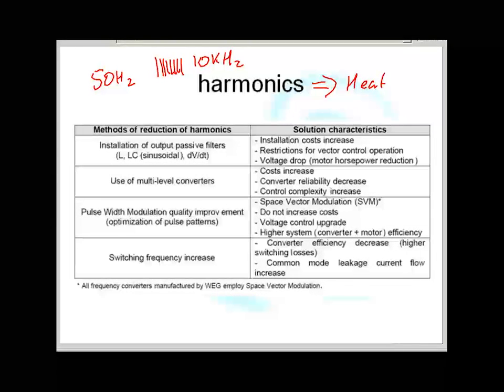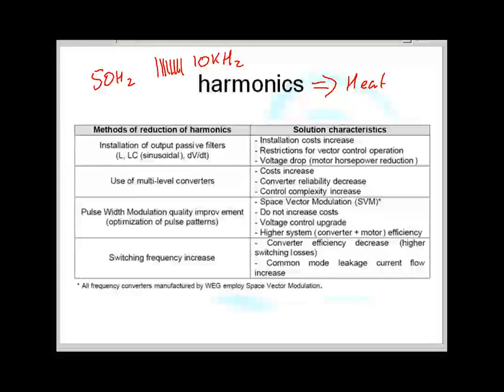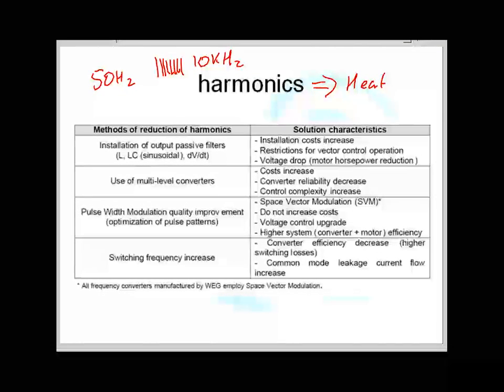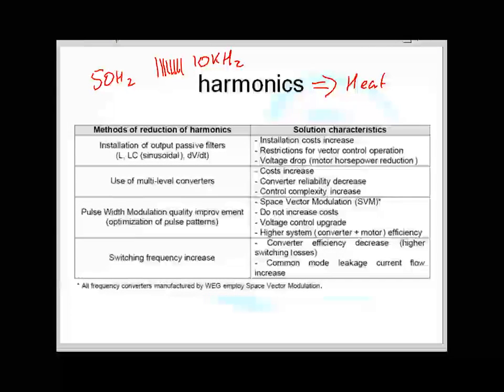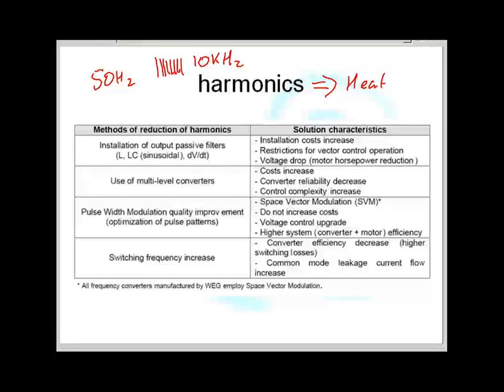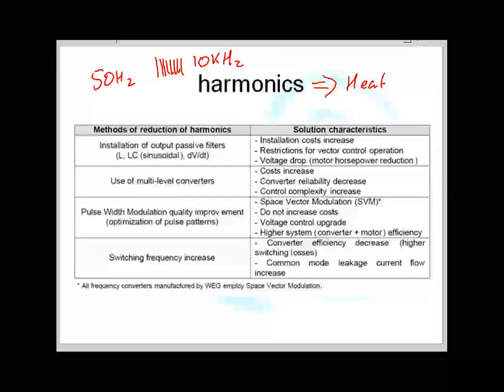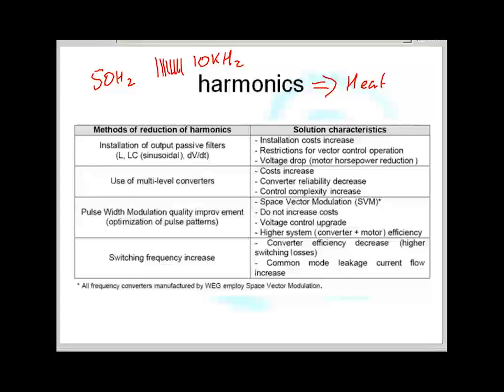So, there are solutions to this. One solution is to install passive filters in the VSD. Now that would make the VSD more expensive. It would also restrict how quickly we can change the frequency, because it's a filter. Filters restrict how quickly you can change things.